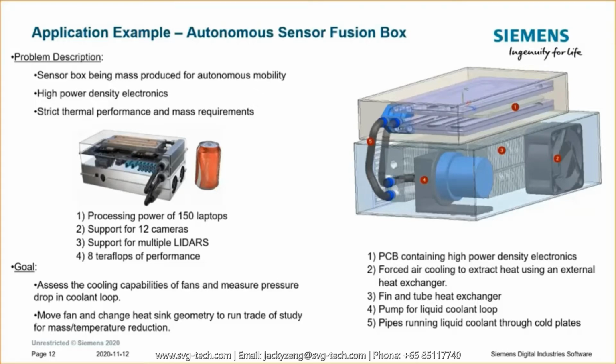So here we have a few things going on. We have multiple domains. So we have air, water, we have fans, we have a printed circuit board in there, which I will show you how to bring in using our EDA import. And then the goal of this analysis is to assess the cooling capabilities of the fan, measure the pressure drop in the coolant, and then